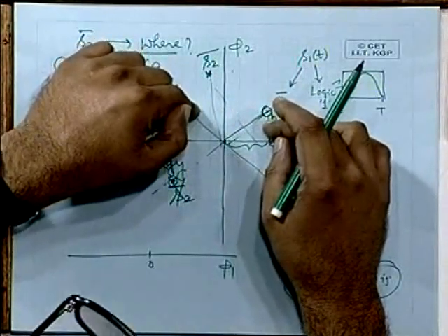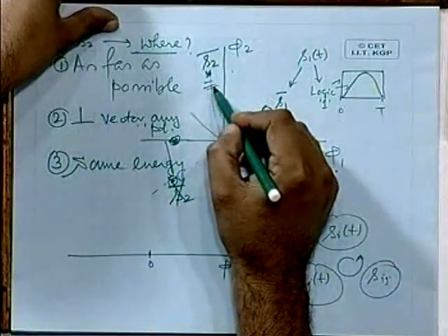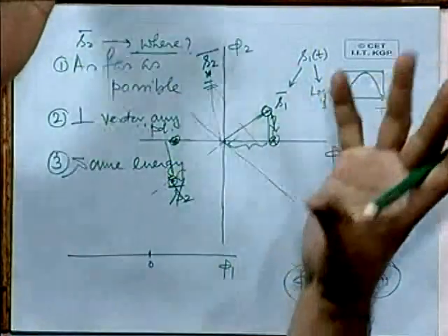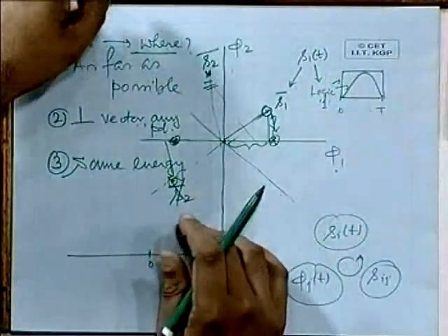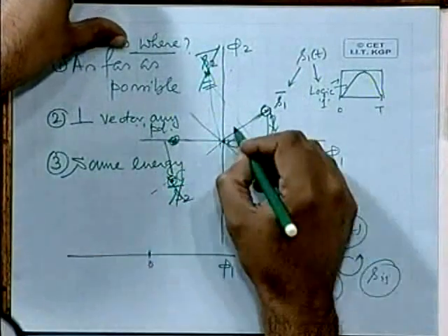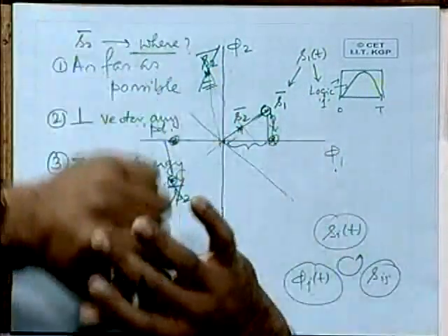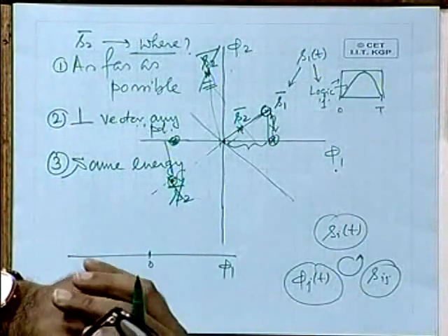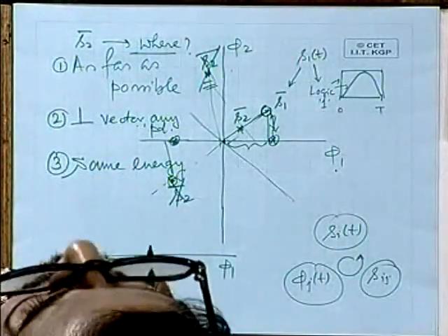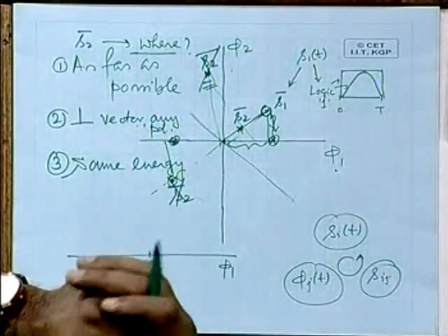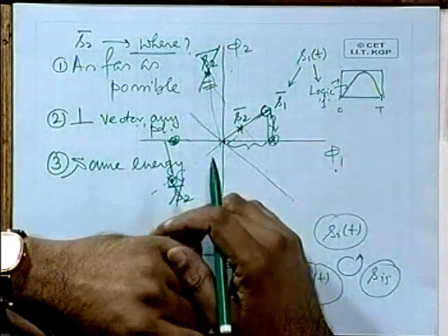But in some cases there may be a sense as well, like let me say, not as this one. I am just trying to give you a few quick examples so that you can start thinking about these issues and do some practice. Suppose instead of choosing S2 here, I have chosen S2 here. Is there anything wrong? So far as modulation scheme is concerned, no, acceptable. What is the difference? The energy is different. So, one I am transmitting with a higher energy, the other with a lower energy. Can you quickly guess whether you can think about some modulation scheme which may follow this?